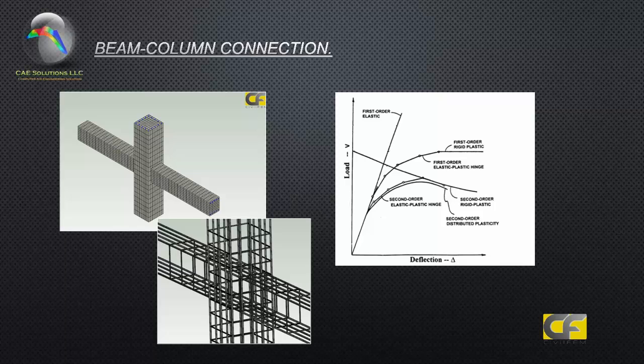we also have, when we take into consideration the P delta effect. However, we still have what is called the distributed plasticity formulation models, where the variations of the stress and the strain through the section and along the member are captured in more detail by means of nonlinear hysteretic constitutive properties. And all of these are captured by small finite elements, which we are using in this model. We have defined solid elements, and then we make automatic meshing, and all the inelastic behavior is captured by these own micro finite elements.